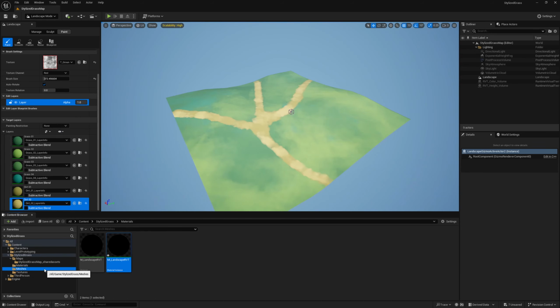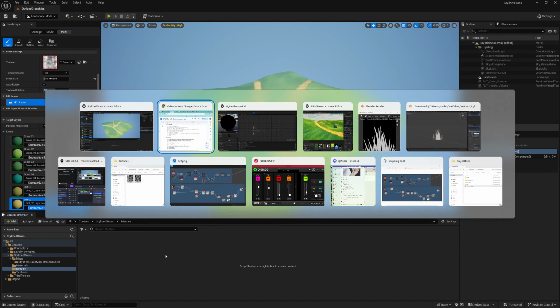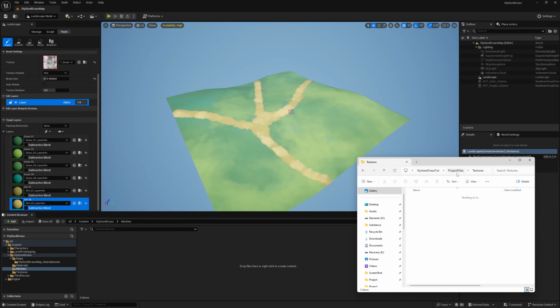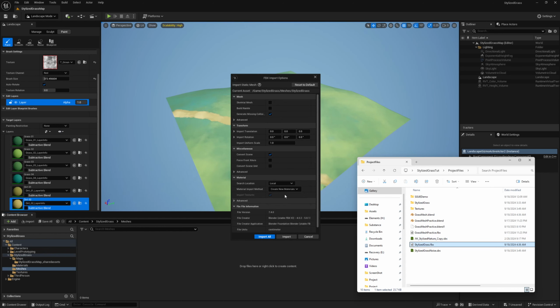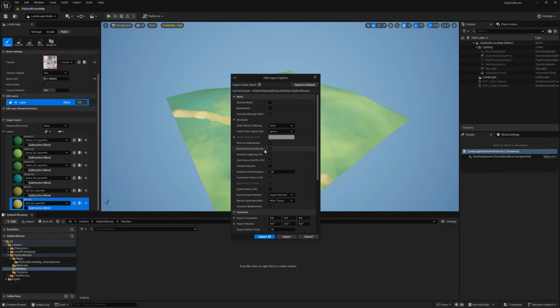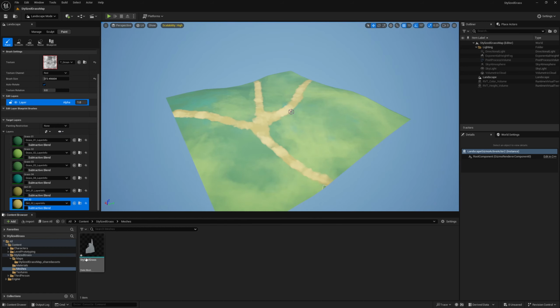Back in Unreal, I'm going to go into the Meshes menu, and look for the folder where I had exported my FBX. Let's just drag it in there. In the Advanced section, I want to make sure Combine Meshes is checked. That's typically the only thing I look for, and I make sure that Do Not Create Material is also checked. We don't need a texture yet. Let's import it all, and we have our mesh.